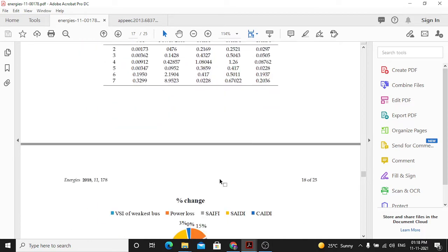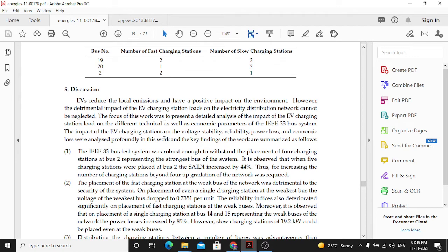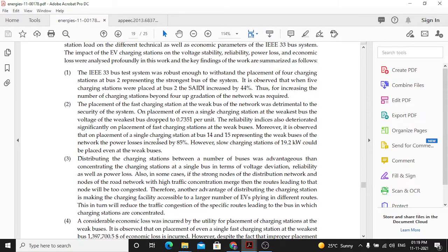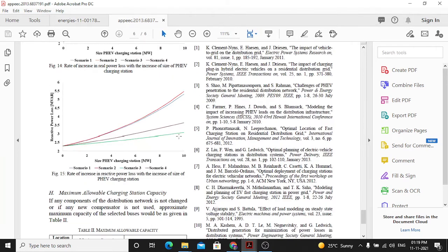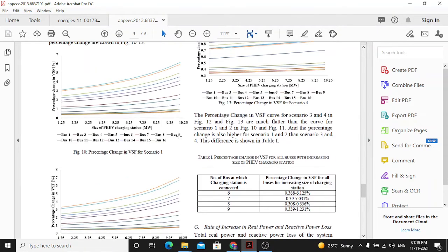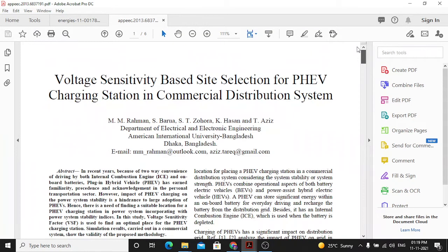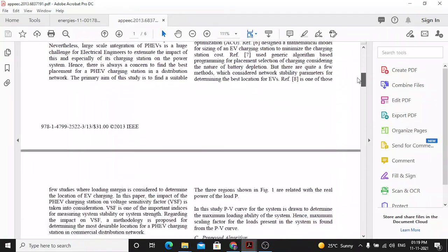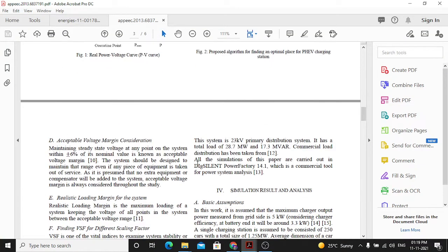Next, say this is the grid connected DFIG based wind energy conversion system. In a grid connected DFIG based wind energy conversion system, if any fault occurs over here, this is the fault, and let us consider that this is the voltage profile. Throughout the operation, we have to maintain a constant voltage profile at the PCC, at these bars.